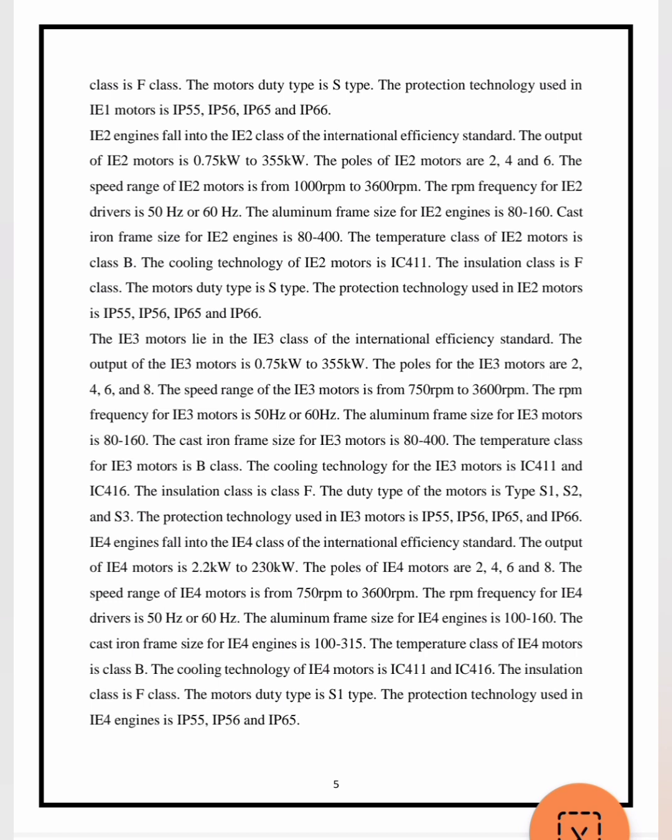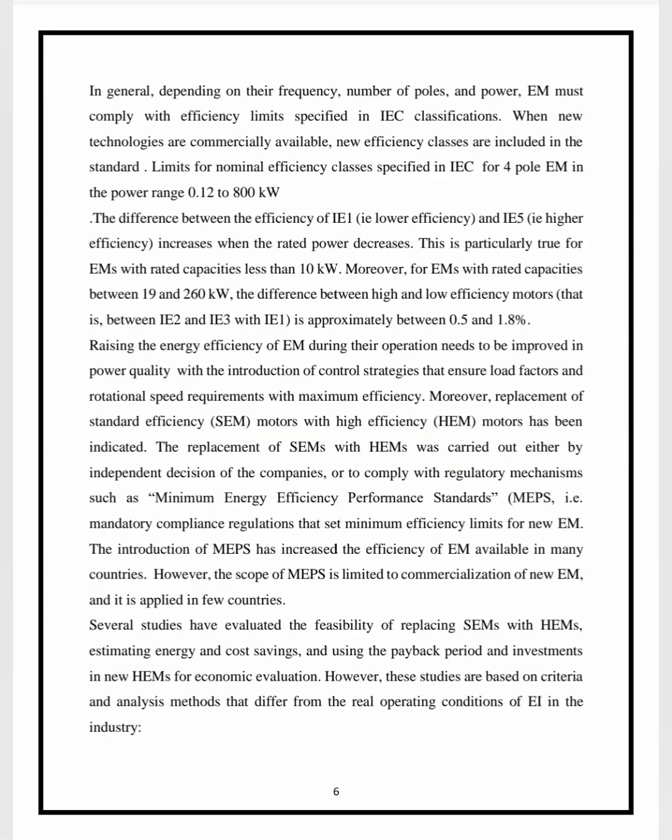All the efficiency motors belong to the F class. The motor duty type is S1 type. The IE3 motor has duty types S1, S2 and S3, while this one has just S1, meaning it has the standard efficiency, but its own efficiency standard is the super premium efficiency standard. The protection technology used in IE4 motor is IP55, IP56, and IP65.